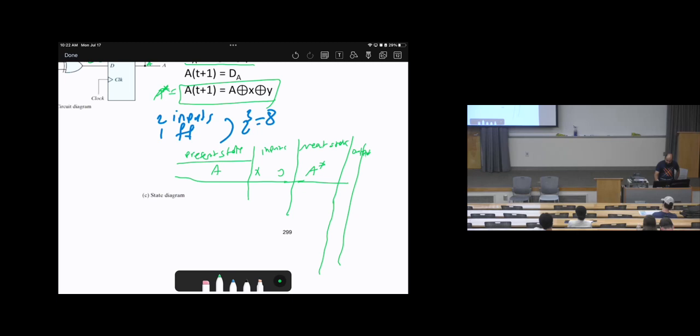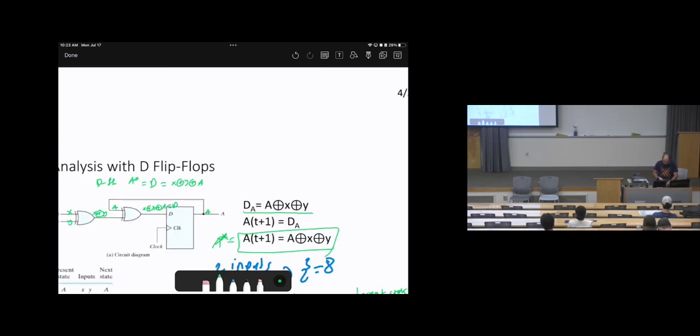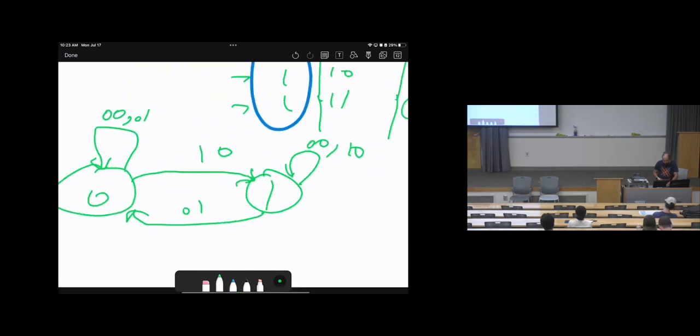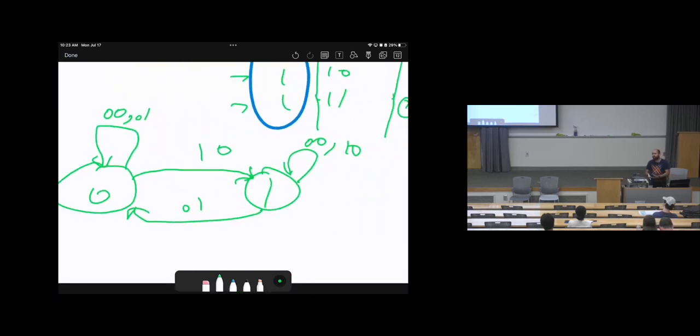Since we don't have outputs, we cannot say to use Mealy or Moore's model, because again, there are no outputs. Mealy and Moore's models differ just in the location of the output. Since there are no outputs, just draw the state diagram. That is applicable for everything. So for this state diagram, as we did here, for example, there are no outputs, so it is neither Mealy nor Moore's model. It's just a state table, whatever.